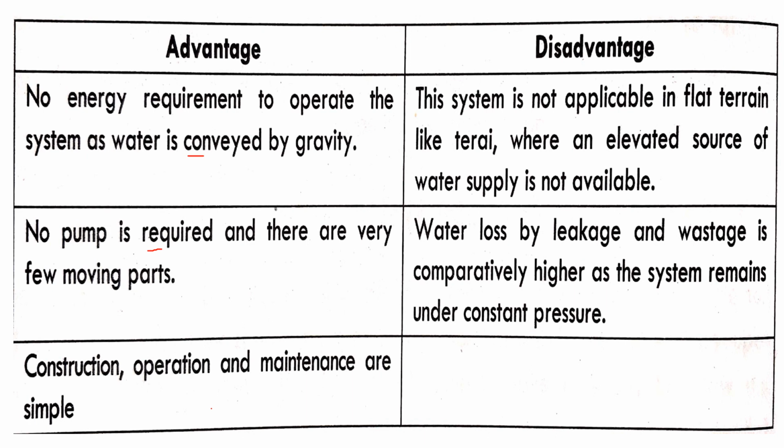But disadvantages, like it is not applicable for flat terrain, like usually in Terai areas it is not good, right? Or when there is elevated source, it is not suitable for those places. And similarly, water leakage is high in this because the water constantly flows at same constant pressure, right? So that water leakage is usually seen in this type of system.